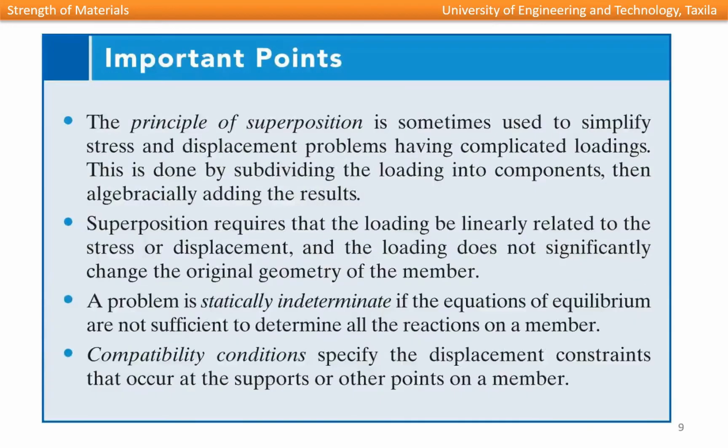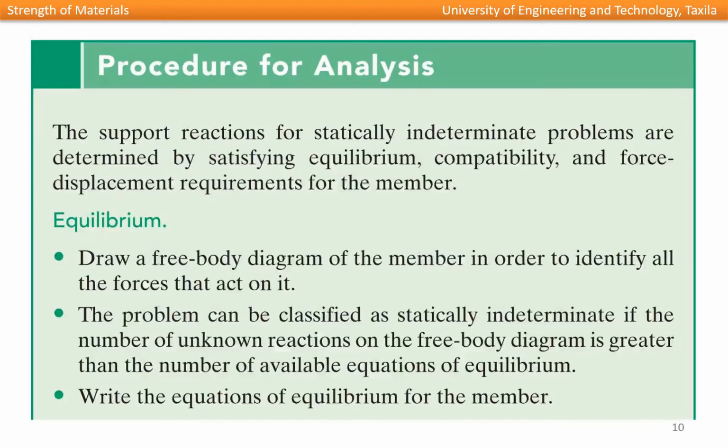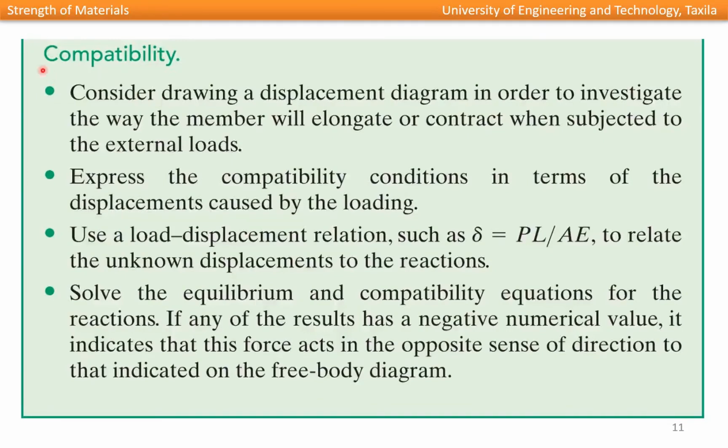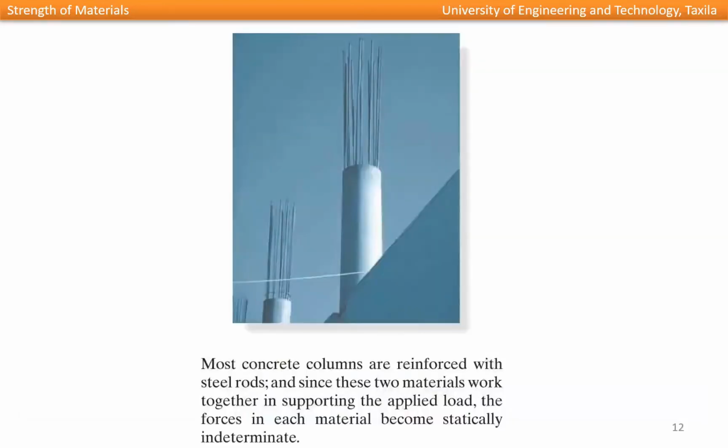Okay. These are the important points related to the law of superposition and a statically indeterminate problem, and that is the procedure for analysis. First we have to write the equilibrium equations, then we have to write the compatibility conditions, and then using a load displacement relationship like delta is equal to PL over AE, we can relate the unknown displacement to the reactions. Finally, using the equations of equilibrium and compatibility equations, we can find out the unknown reactions or forces.